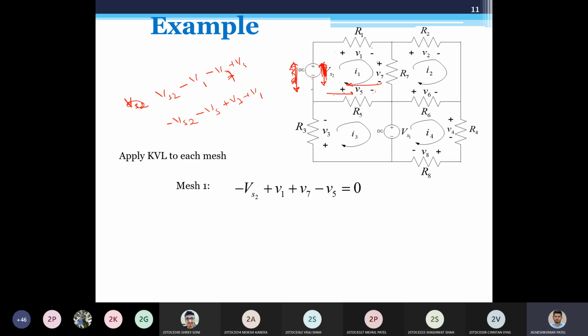Okay, see here also negative to positive, and this one also is negative to positive, but this is voltage source, so negative to positive is actually considered as negative. But if it is a voltage drawing element, and in that case if I'm going negative to positive, then I'll consider a positive sign, because this is the voltage consuming element or passive elements. So passive element will change the consumption. So either of these two equations is correct. And if you look at detail of this equation, you will see whatever is the negative here will convert into positive, like so. It is the same equation.